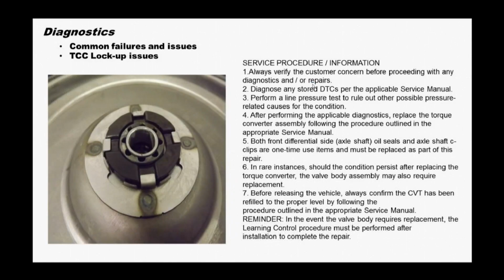Here's the old thrust washer style. They're replacing this thrust washer with the bearing in the newer converters. After replacing the converter, use the correct fluid, of course. Do your relearns.